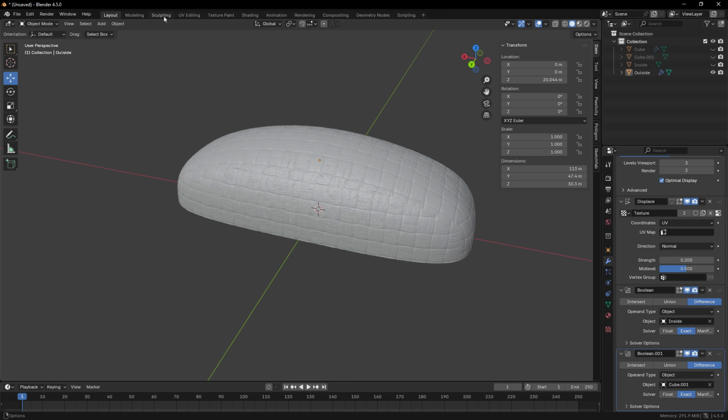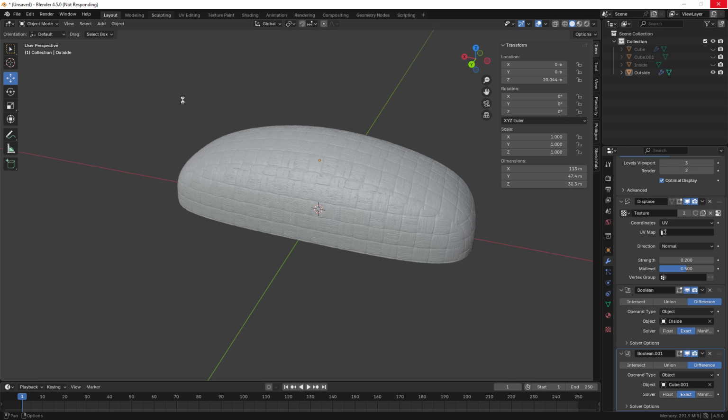In Blender, you can also use sculpting tools. So some of these add-ons like Polygon will have sculpting tools that you can use and just basically drag the brush across your model and create that texture in that sense as well. The same things will apply. The mesh resolution, basically the size of those triangles or quads, is going to have a direct impact on the quality or the detail that you can get out of doing something like this.